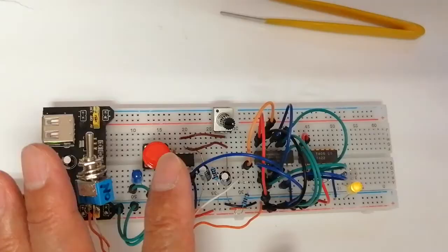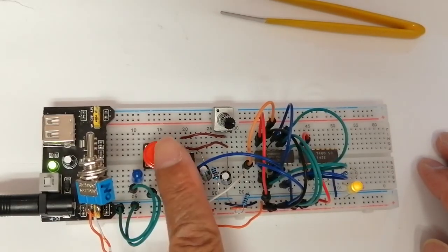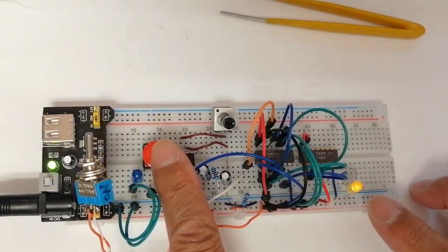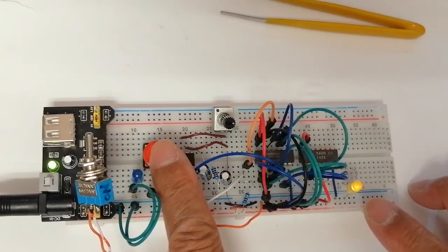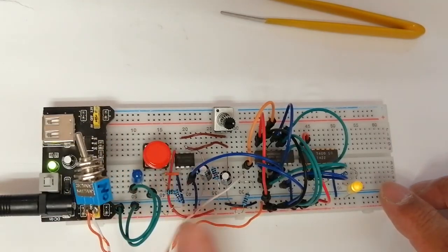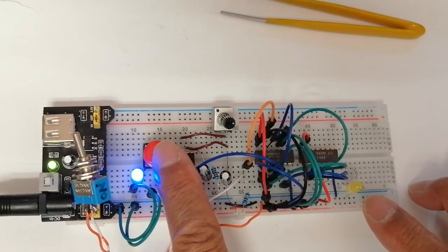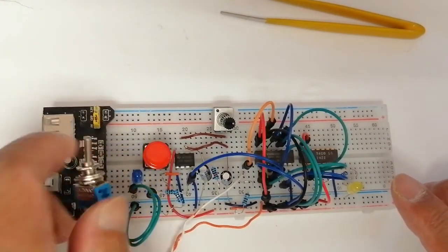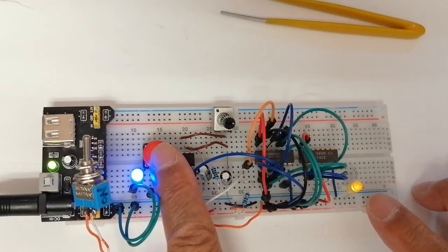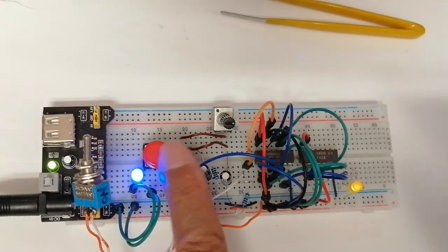But once you change it, okay, now I short circuit the ground to the input, that means low. Then this light stays on. Okay, there was a loose wire, that's why. Now I bring it to high, then this guy starts alternating. Okay, so very slow clock. Each time a clock comes, it alternates. But once you turn on this one, that means low, it doesn't change, it stays on. So exactly as expected, this is the output of the NAND gate. Okay.